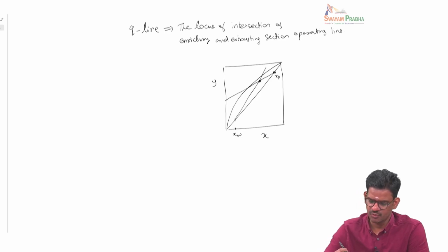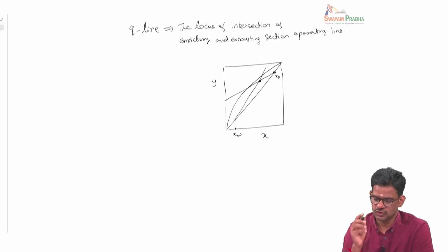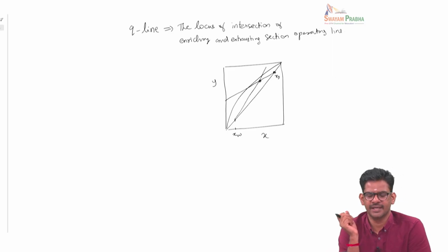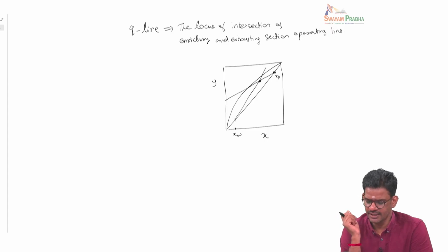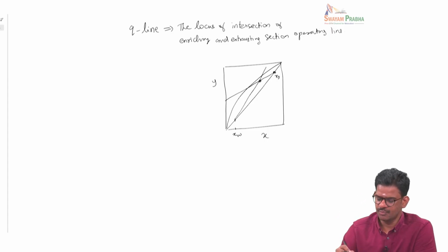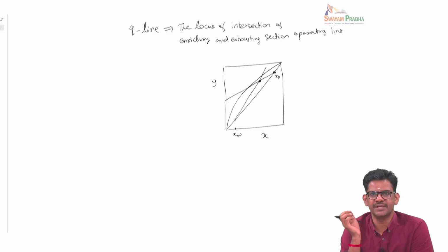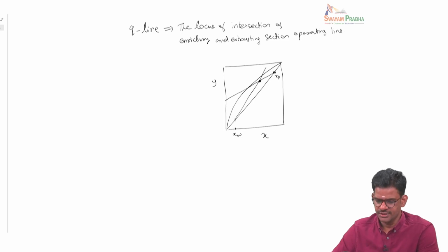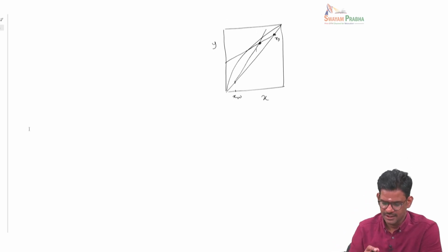So you see that there is a point at which they intersect. The slope of these lines depends on the flow rates of liquid and gas. What we are going to do is look at the possible points at which the two lines will intersect, and we can obtain this by simultaneously solving the two operating lines. So let's write the operating line equation for the enriching line.